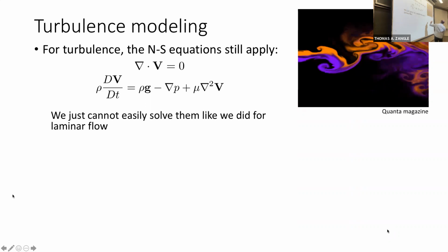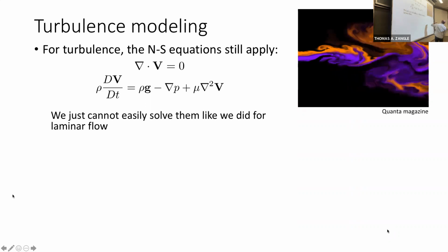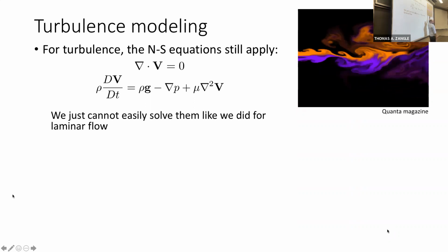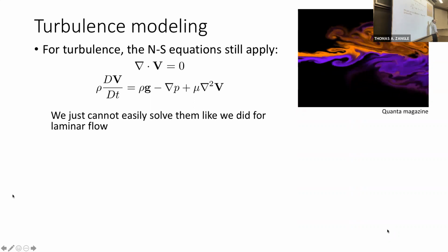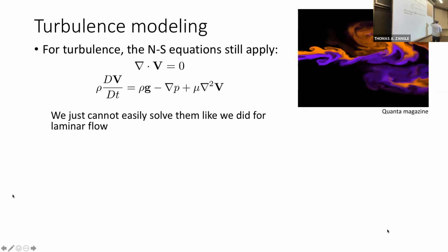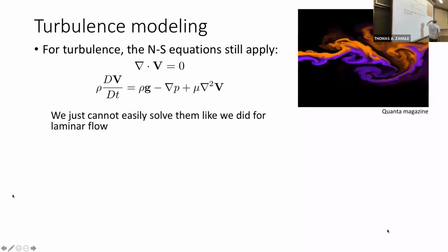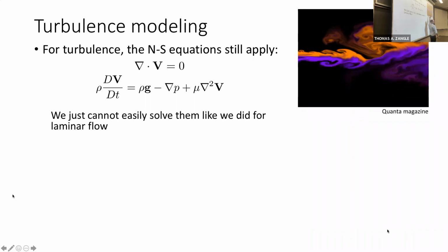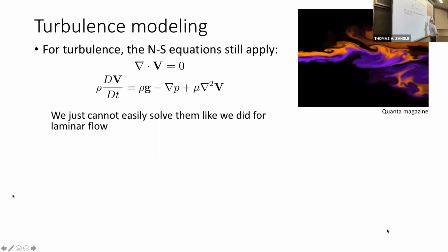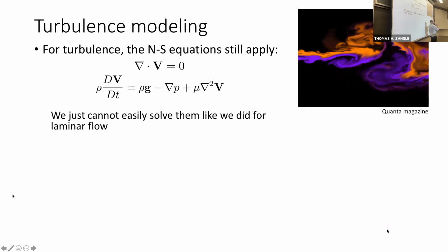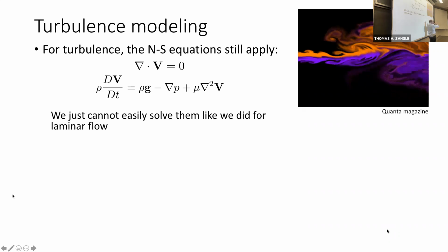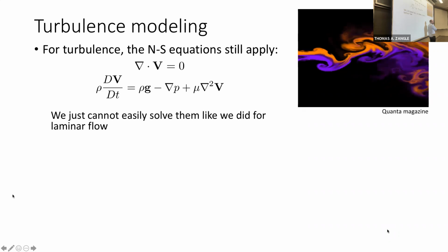So one idea of why that might be, you can actually kind of see in this movie here. We primarily have flow from left to right. So we primarily have flow, let's say, in the x direction, right down the screen. But because of that flow and this turbulent flow, we have the formation of eddies, which are creating smaller eddies and smaller eddies still, all the way until they're dissipated by viscosity, right? So we have eddies across a large number of length scales. And those eddies are these little vortices within the flow that are created by the flow.